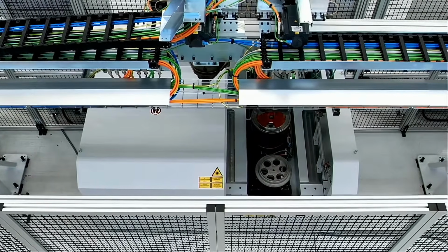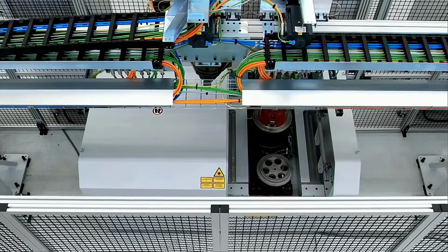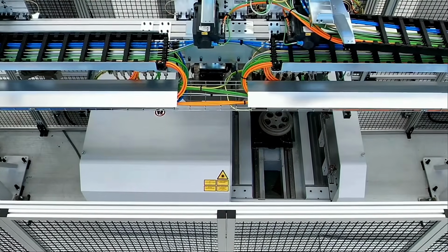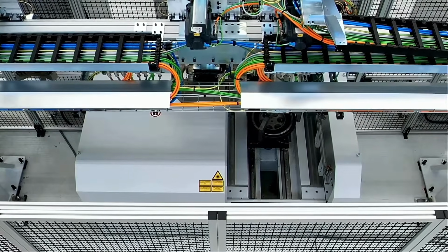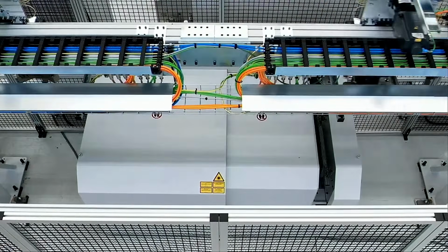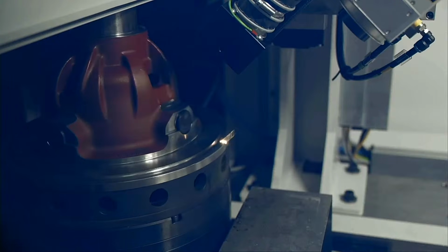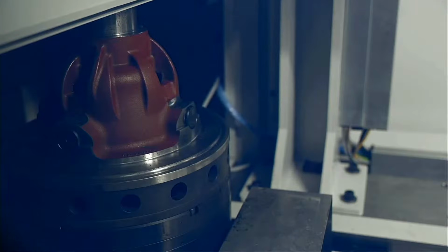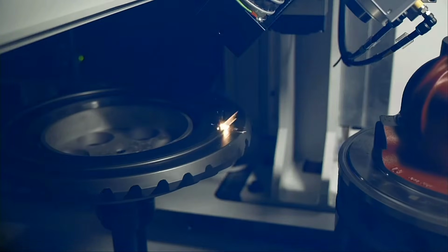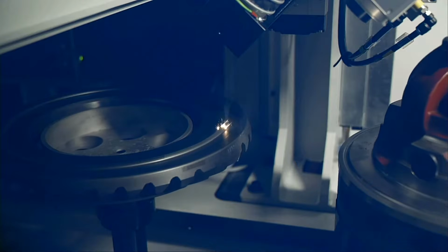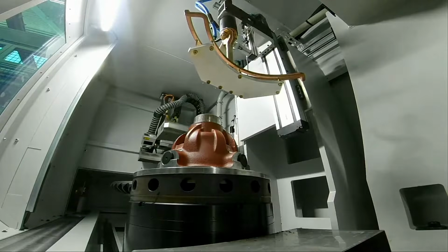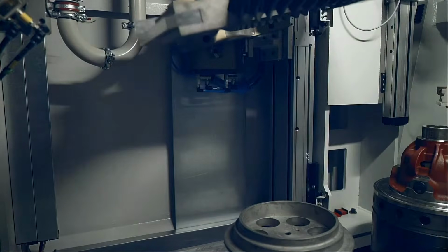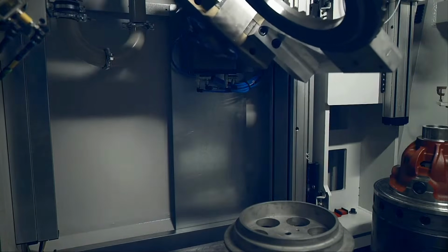The machine itself is more or less similarly equipped as the first one. Here we have loaded the first welded component, and then we load the ring gear as well. Then we start with the laser cleaning operation, first for the cast component and then for the ring gear as well. So the idea is a turned workpiece at a fixed optic. Here we are using a scanner optic and a 200 watt pulse laser, and then we again move the ring gear up and turn it 180 degrees.